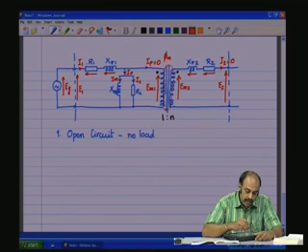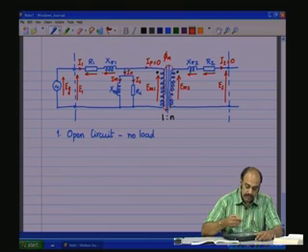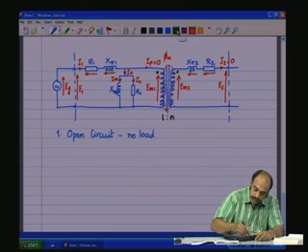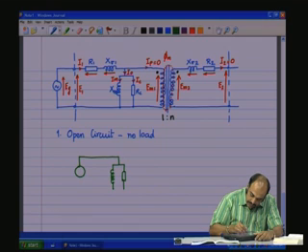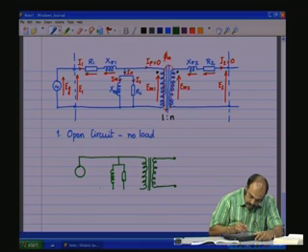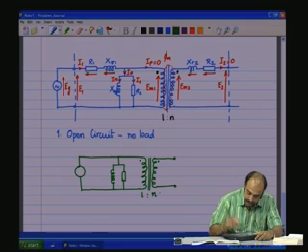These can be neglected, that is R1 and X sigma 1 can be neglected, which means the equivalent circuit under no load condition could be simplified as this: just the magnetizing loss component followed by the ideal transformer with the secondary just open circuited, dot polarities 1:n.